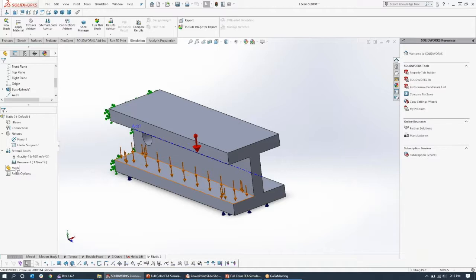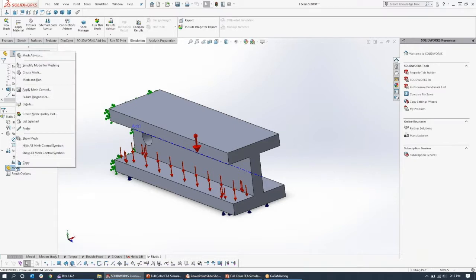This is the step where the overall solid geometry of the part is broken down into small pieces, which can be simulated independently, well, not exactly independently, but they can be simulated as singular components and relate to one another rather than trying to model a complex part in an exact analytical way. So the next step would be to mesh the part, and this would break it down into those small pieces,